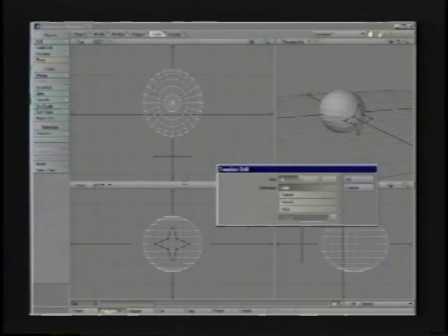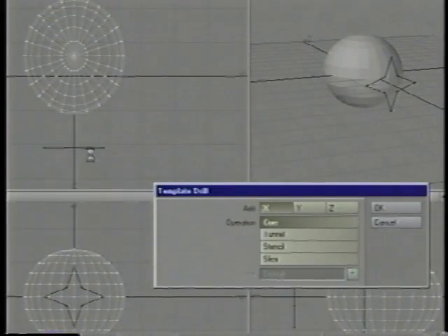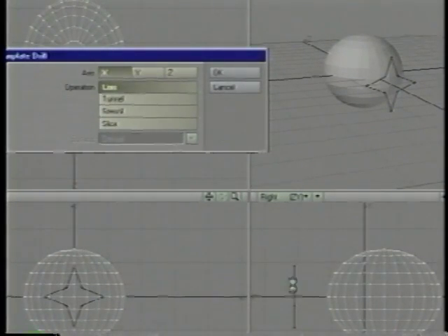And the only axis that's going to work right now, the way this is set up, is the z-axis, this axis right along here. If I were to do the x-axis, it would project along this way, which is not going to work. And if I wanted to do the y-axis, it would project along this axis, and it wouldn't ever hit the object that I want to drill into.